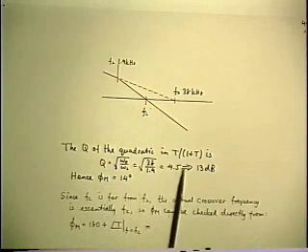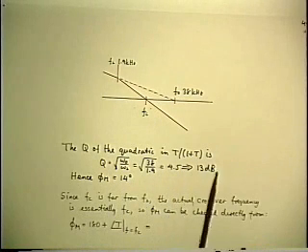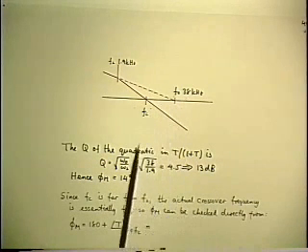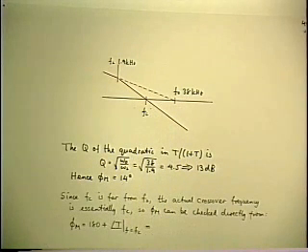And when you plug the numbers in, the Q is 4.5, 13 dB. And that corresponds, of course, to a very small phase margin, only 14 degrees.